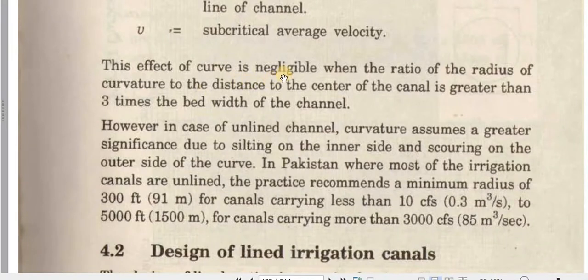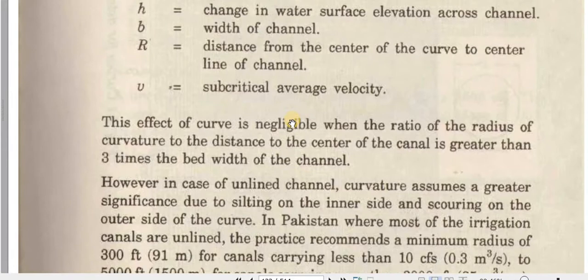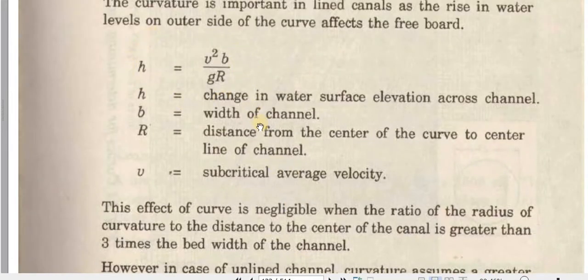And this effect of curve is negligible when we have a large curve, when the ratio of radius of curvature to the distance to the center of the canal is greater than 3 times the bed width of the channel. If the radius of curvature, which is from the center of the canal, is greater than 3 times the bed width, then we can say there is no effect of curvature, and we do not need this equation in those cases.